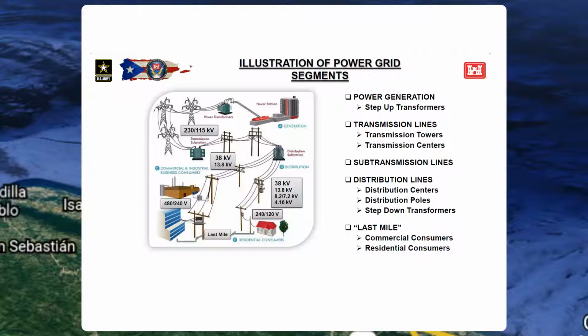In carrying out one part of my research, I stumbled across this diagram which enlightened me a lot about the nominal voltages and how they distribute their voltages to their commercial areas, residential areas, and so on. So I made the decision that the low side for our transformer would be 13.8 kilovolts and the high side for our transformer would be 115 kilovolts.